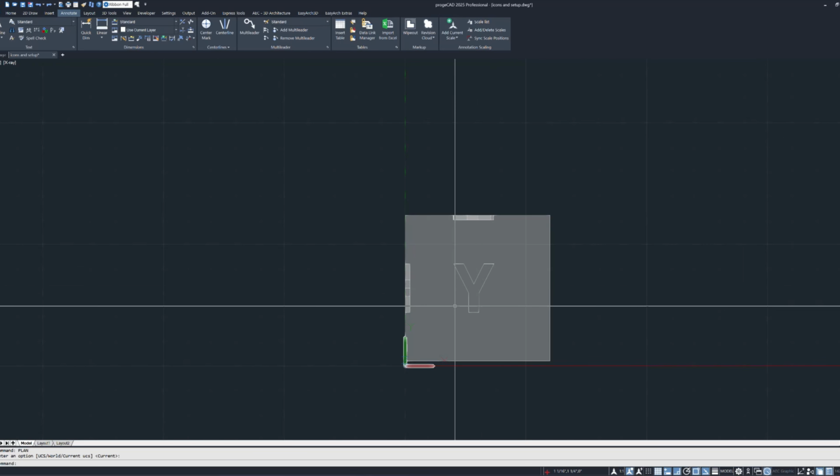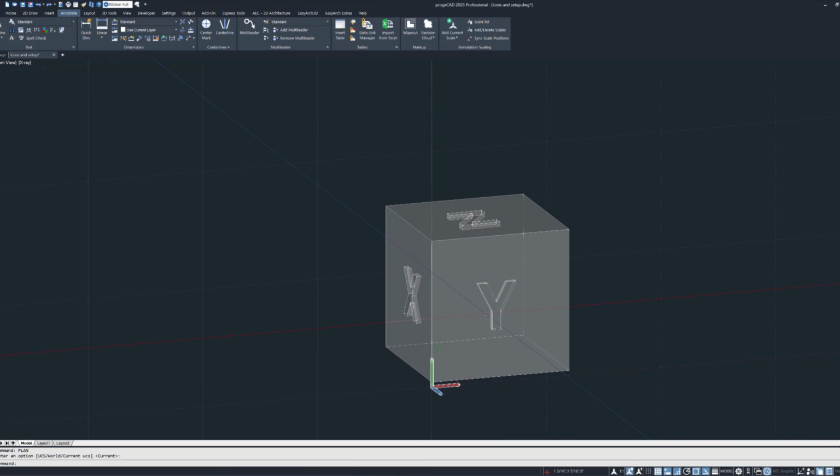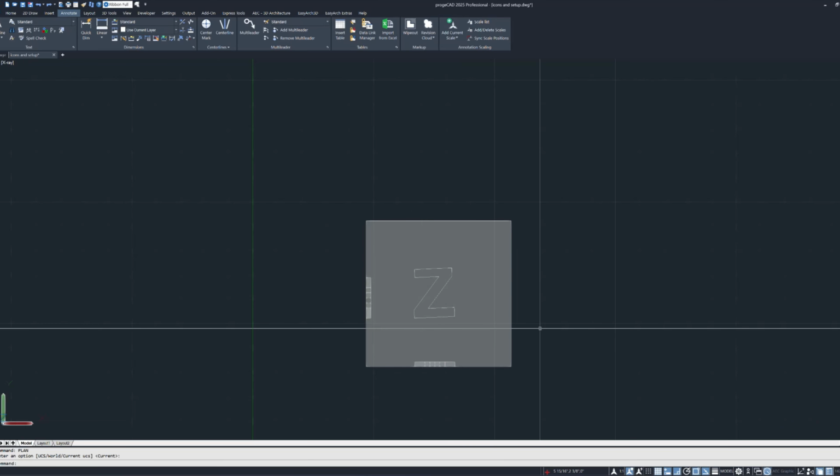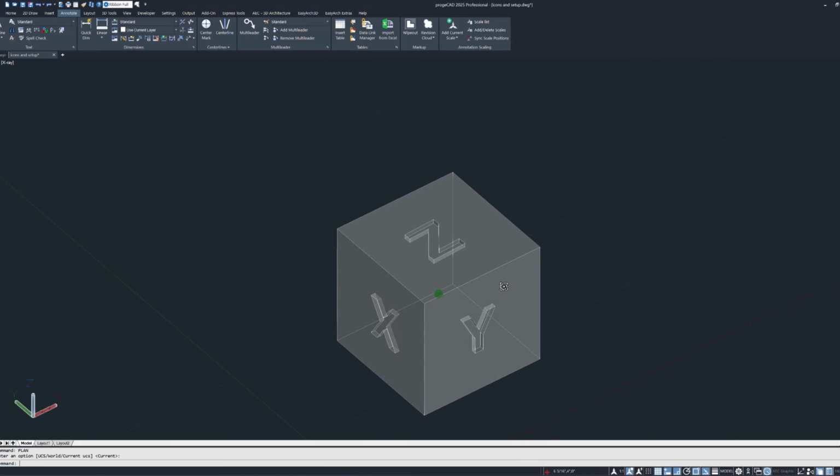WBlock is a command in CAD that saves any selection of objects to an external file in DWG format. The only method of saving a drawing with the UCS and UCS names is to save the drawing they were defined in. WBlock or WriteBlock will not work to save all the definitions of the drawing setup we illustrated in the previous video segments.